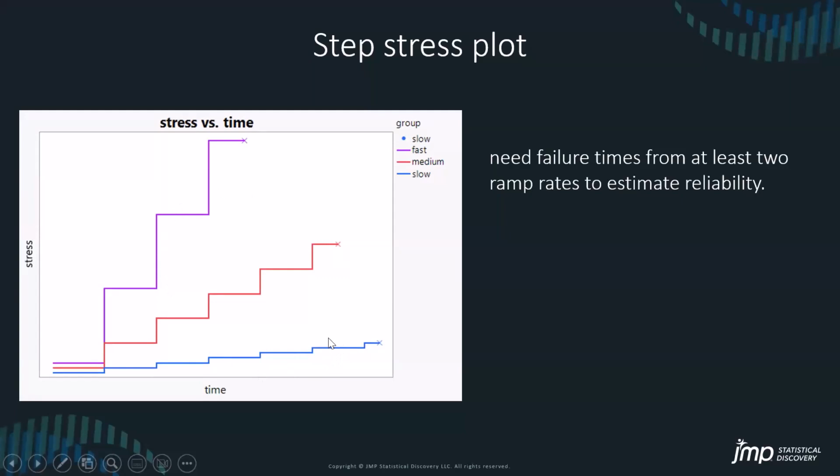So let me just take a step back. When I was in the semiconductor industry, it was very common to run a ramped capacitor test. You pick some fast ramp rate, like 10 volts per second or something like that, and you'd ramp the voltage up on that capacitor until it failed. And then you might do that for a lot of different capacitors. And what you want to do is find out what the failure voltage is and compare that to other batches of wafers or other designs or what have you. And you want to see, is there any difference? I want to make sure my process is in control. I want to make sure that the voltages are all the same, right?